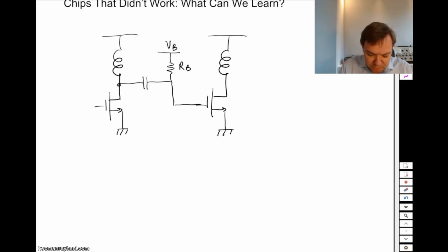Well, what I'm doing here with this inductor, I'm basically tuning out all the capacitors that I have, a capacitor here and a capacitor over there. So I'm just using tuning. I'm not doing any matching. And that's typically what people would do at RF frequencies, let's say below 10, 20 gigahertz.